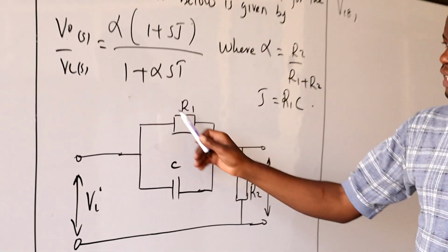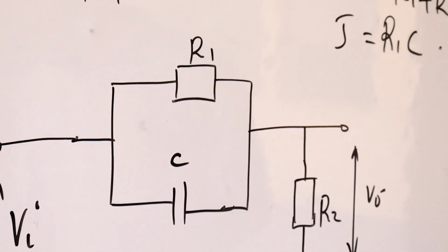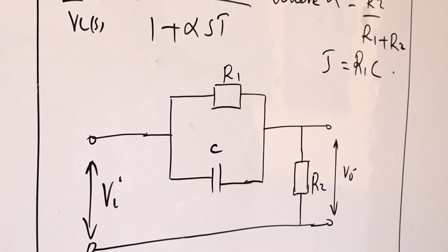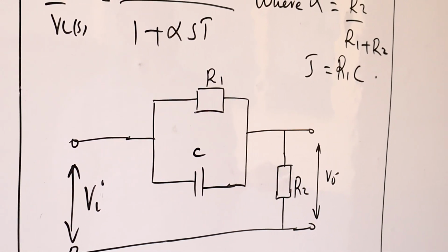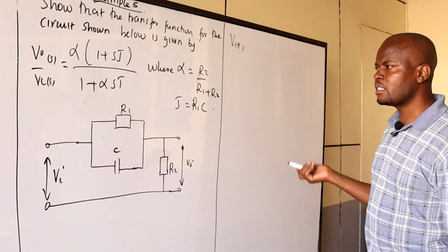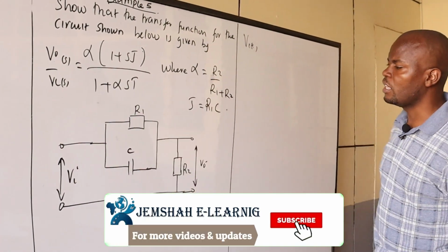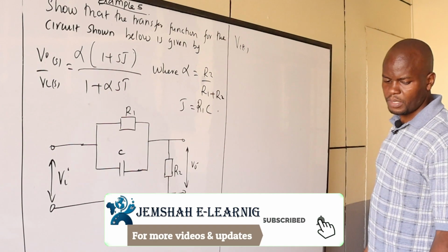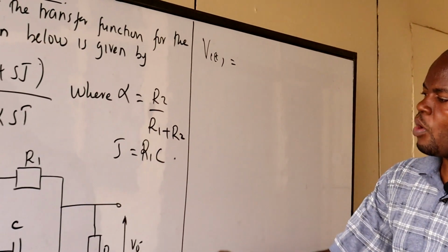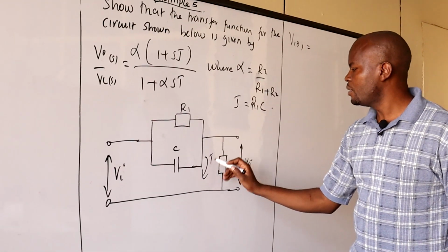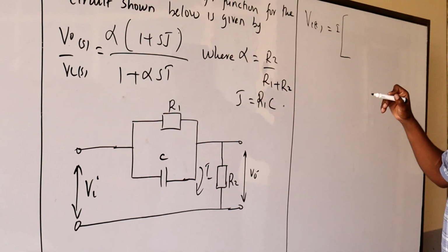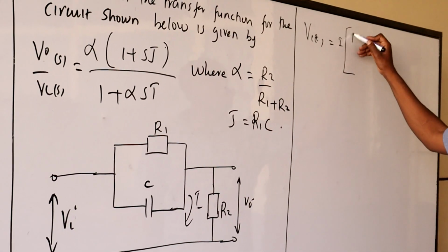The Vi of t is the same as the voltage that is here, and we can use the method whereby we find the voltage by the use of the resistance in parallel to get the impedance there. If they're in parallel, then there is a common I for both. So we can simply multiply I by the total impedance in parallel, which will now be R1